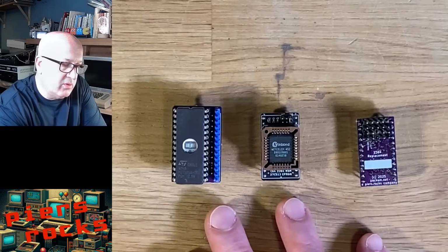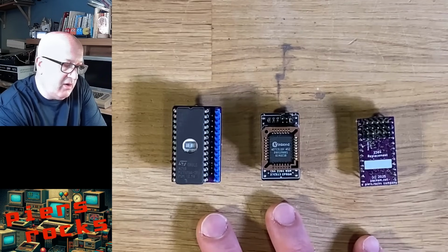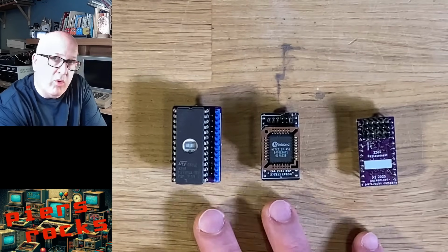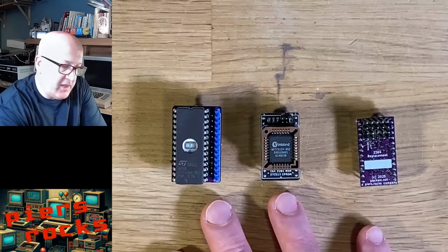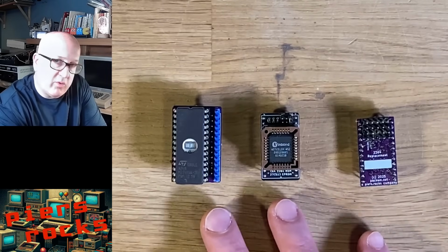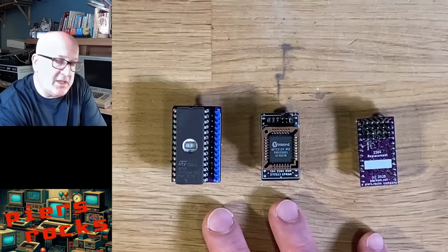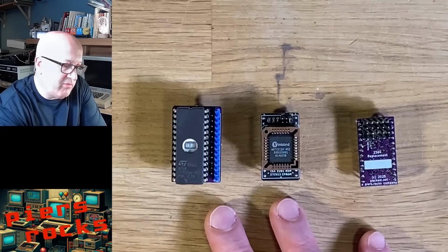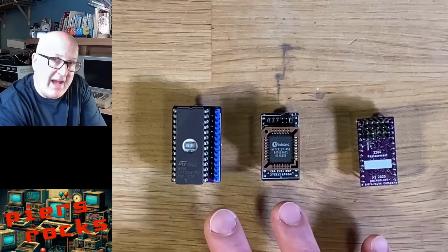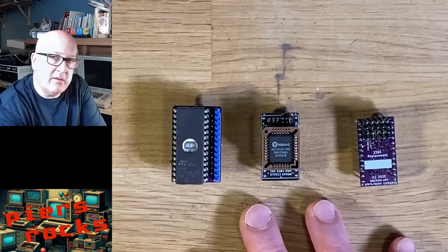behavior with these boards. You can buy boards that allow you to change the chip select behavior of the replacement board. Those are typically implemented using one or more NOT gates on the replacement board itself, and either use additional jumpers or hardware links that you solder up with, say, 0-ohm resistors to permanently change the chip select behavior of that replacement board, which means you can have multiple different images of that type and that exact chip select behavior on the replacement board. But if you want another chip select behavior, essentially you need another board.